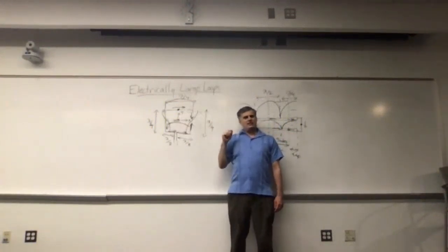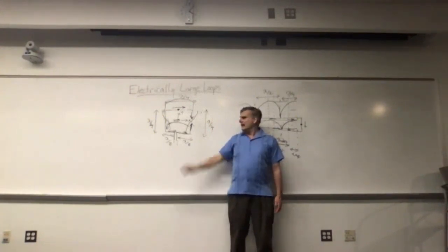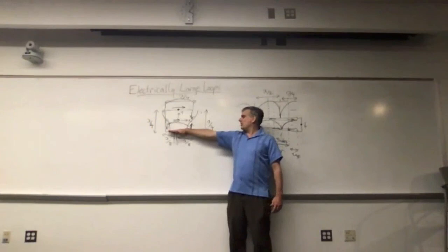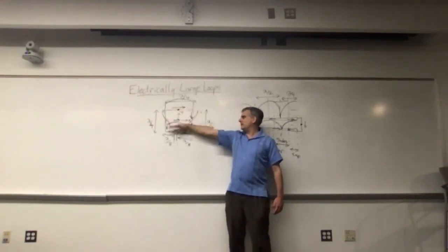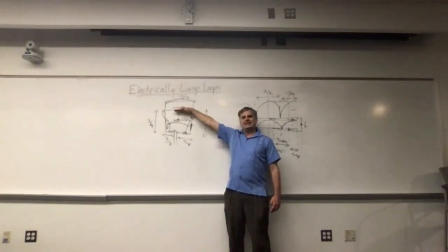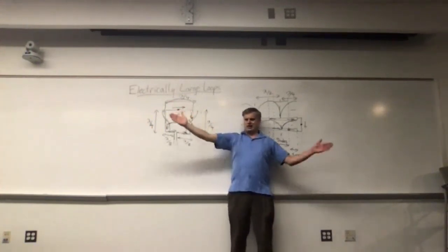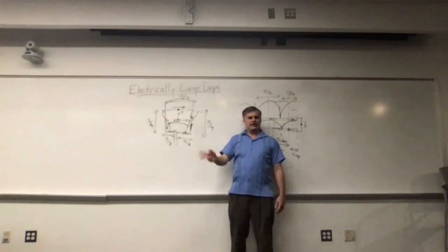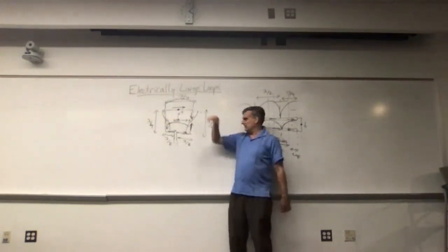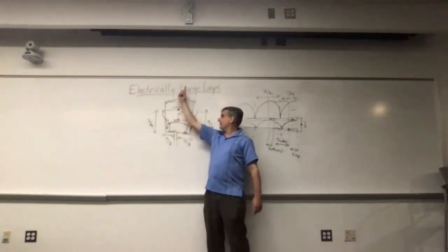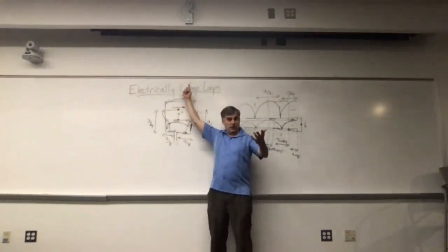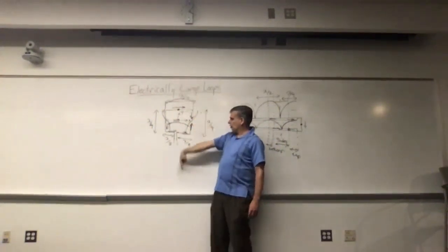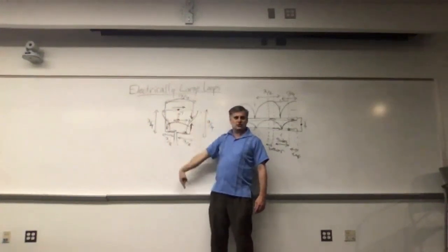So it's not going to be complete destructive interference, but it's not going to be full constructive interference either. When this radiates to here, they're radiating in phase, but when the wave from here gets to this point, it's 90 degrees out of phase, which is kind of like six in one hand, half a dozen the other. It's adding to it a little bit, but it's not like it's aligned. So you're right, this will radiate in this direction pretty well, and you get some partial constructive interference in this direction.